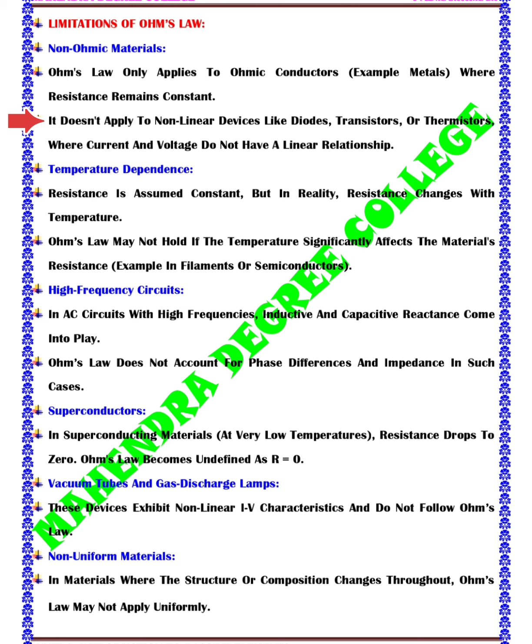Ohmic conductors means these materials exhibit a linear relationship between voltage and current, meaning their resistance remains constant regardless of the applied voltage. Non-ohmic conductors means these materials do not follow Ohm's law. Their resistance changes depending on the applied voltage or current, leading to a nonlinear relationship between voltage and current. Examples of non-ohmic devices are diodes, transistors, thermistors, light bulb filaments.